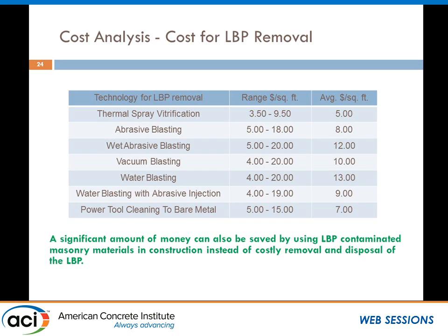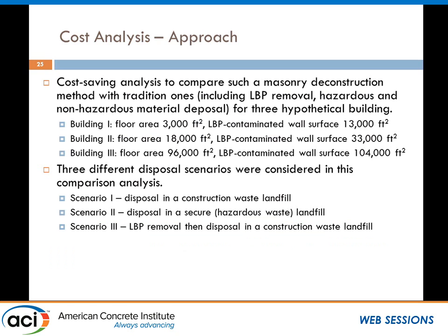One other thing we did is to check out the cost effectiveness of this. These are cost information for normal practice of lead-based paint removal. As I say, one typical process is to remove lead-based paint before you demolish a building. So you can see, depending on the different practice, you can have from $5 per square feet up to $12 per square feet. Different kinds of practice. Average is about 9. So that tells you a good amount of money will need to be spent if you follow this practice.